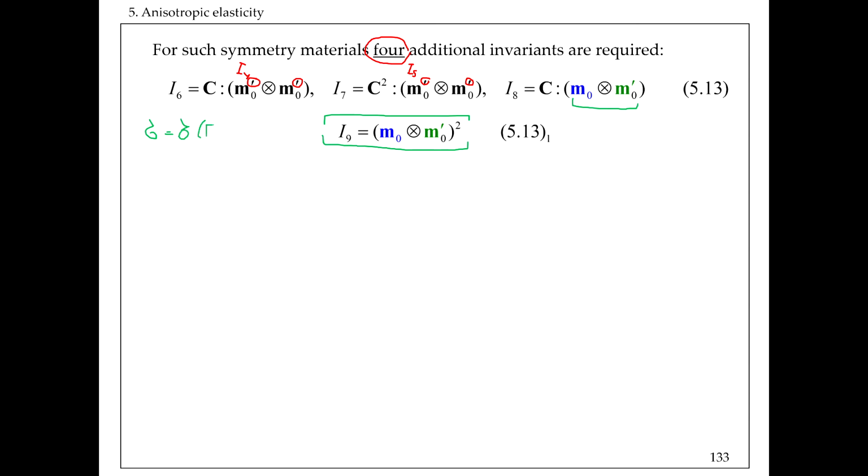That is basically what the constitutive law is. If we recall where the contribution to stresses comes from, at a certain point we will need to take the derivative of that invariant with respect to some strain measure, and you can see that the invariant is not dependent on the deformation, it is purely the orientation. Hence it will not contribute to stresses, and basically we don't need to drag it with us.